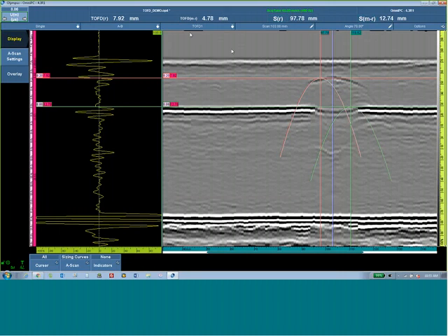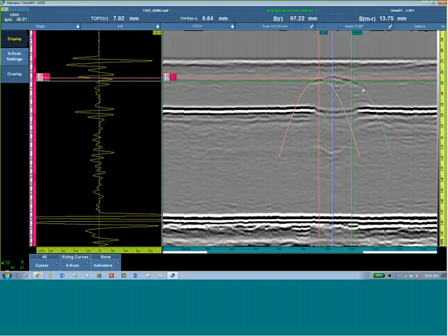It is at a depth of 7.92 millimeters here for a total through wall height of 4.78 millimeters between the back wall or inside surface and top of the flaw. And it has a length of 13.75 millimeters. So we typically oversize flaws in TOFD and phased arrays, so be very conservative. Use the parabolic cursors to identify the flaw.